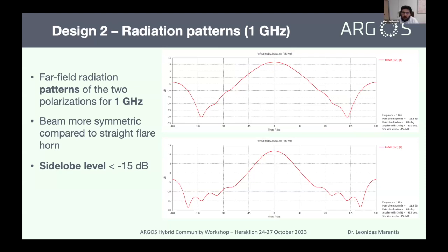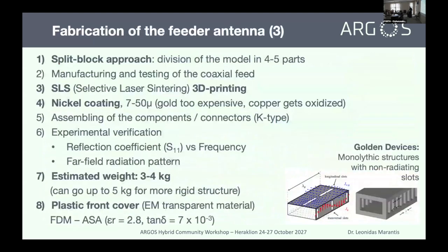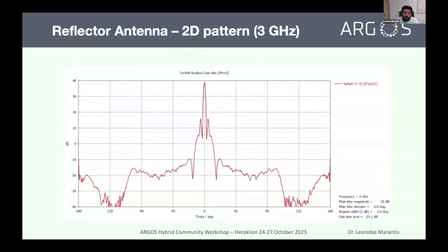Okay. And one other short question: in one of the last beam patterns that you showed, around 2 and 3 gigahertz, I think there are some high first side lobes. Is this something that can be mitigated somehow? Yeah, this is something that we got. I think you're talking about the parabolic dish reflector. Yeah, this one. This is something that we have to take into consideration. It's something that we didn't expect. This is quite a recent result that we got. For sure, we have to do some adjustments and try to eliminate this.